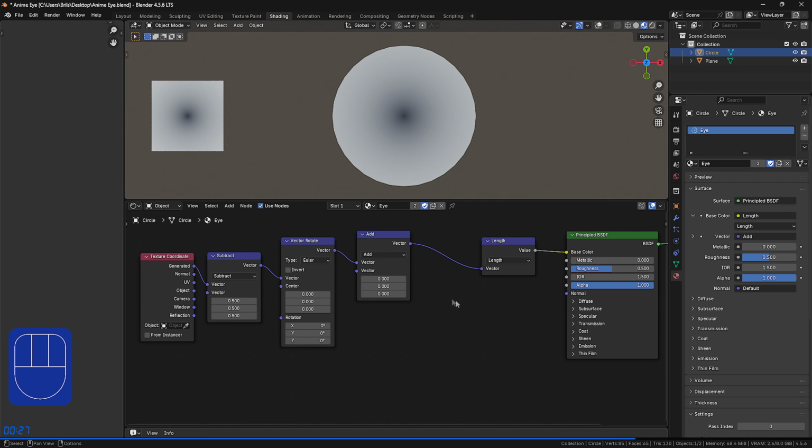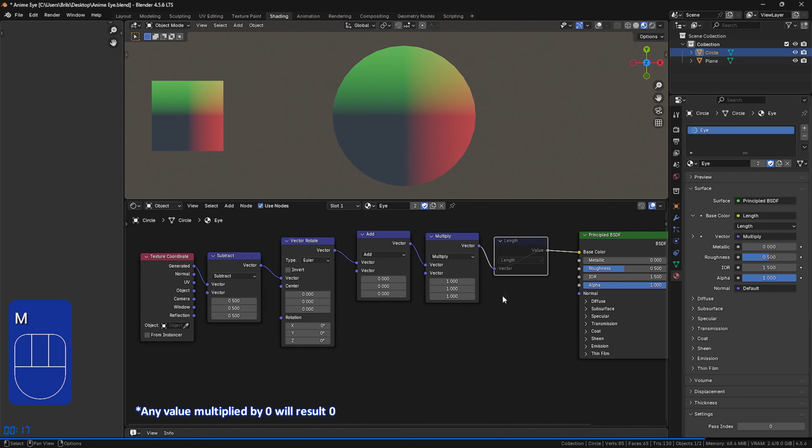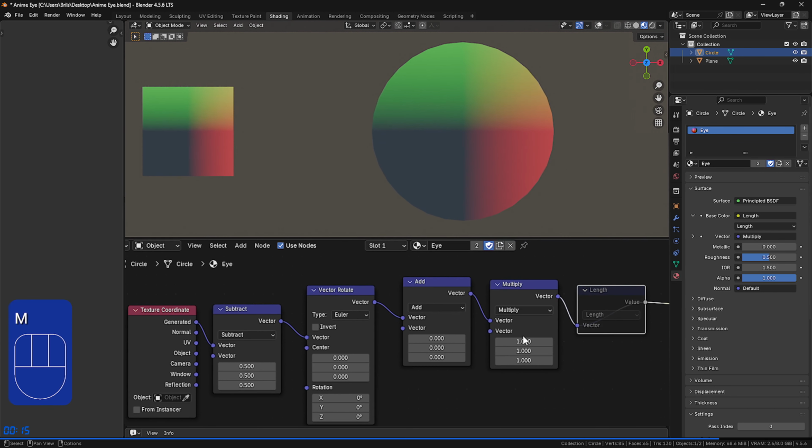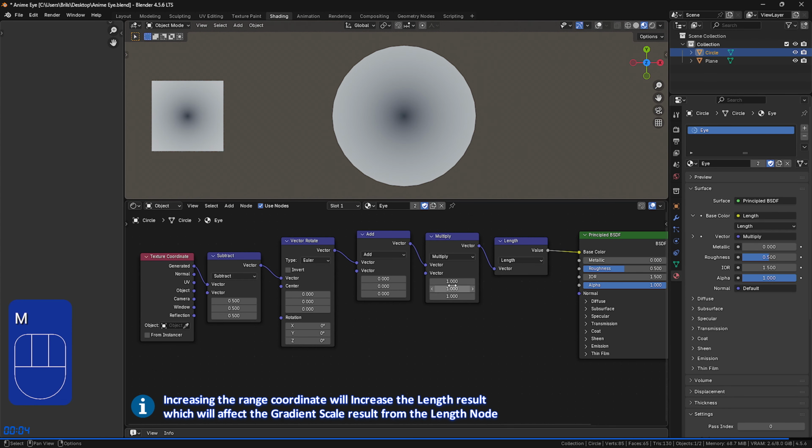Then finally, the scale. Scaling basically changes the distance from the pivot without shifting the pivot itself. We can do this by multiplying the factor. So pivot at 0 will stay 0 and everything else scales inward or outward. As you can see, the green, yellow, and red colors shift closer to the center, and the outward part starts giving white color. That means we successfully increased the range.